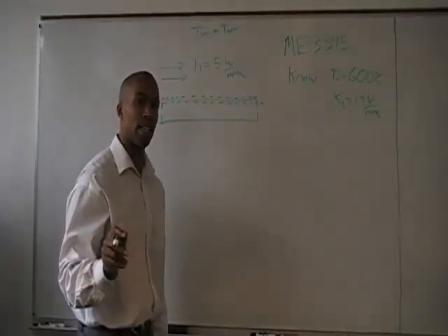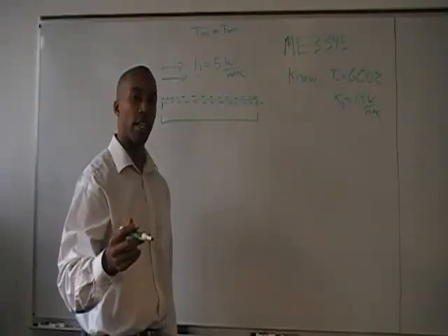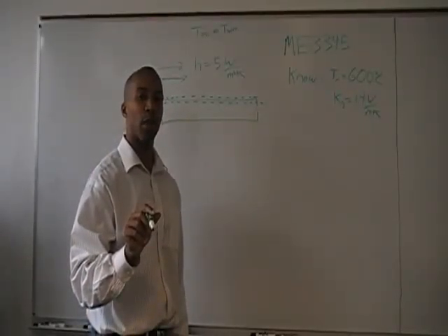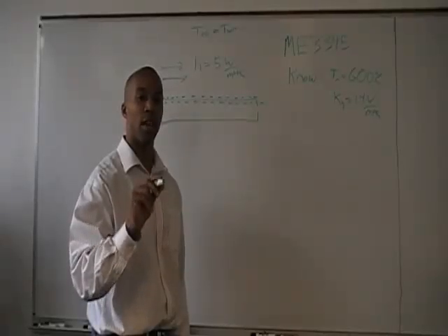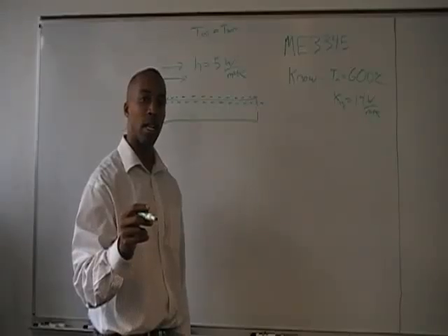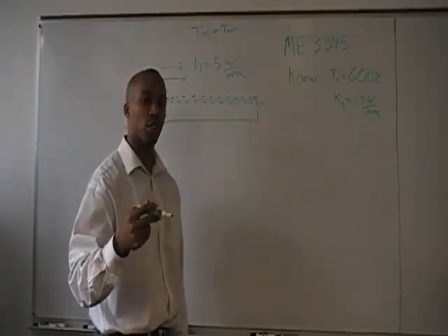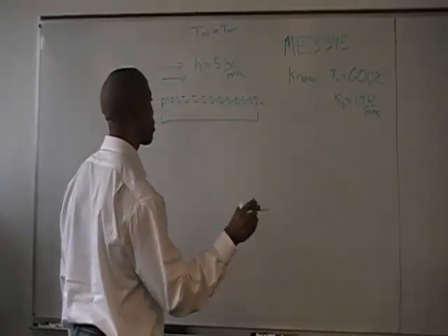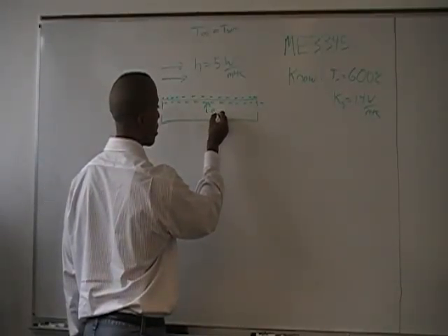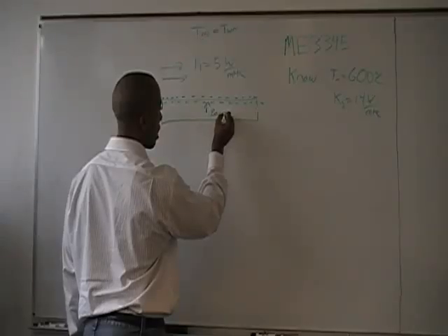What you're also going to find later on, as the math works out, is that the solution is not going to be straightforward. So when you have radiation and you have convection together in the problem, a lot of times you end up having to do trial and error solutions. So you'll see that in a second. But let's start by doing the energy balance at the surface.